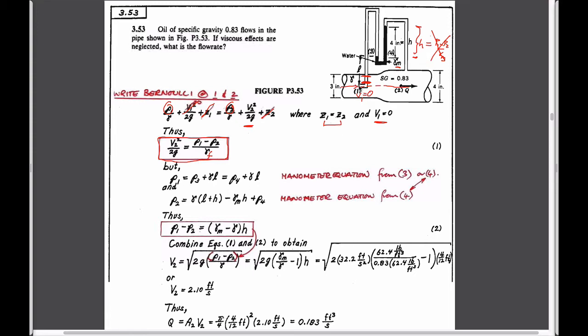So we can use the manometer equations. Take the pressure at point 3. We want to get the pressure at 1, so we go across to here, and then we increase the pressure by adding a height L times the unit weight of the fluid flowing in the system. So P3 plus unit weight times L has to equal P1. This is also the same as the pressure at this point here, since we can go directly across and make the same route to this point as well. That also follows, because P3 and P4 clearly are the same magnitude.